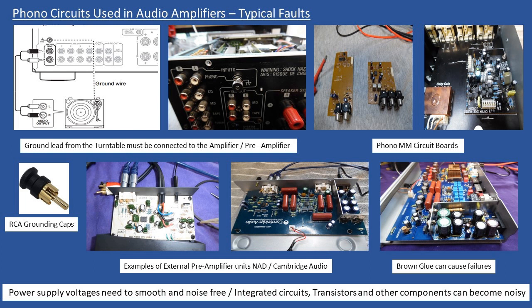You want to localize it down to a specific component, so leave the spray straw in place, and as you press the top, just drop some of the liquid onto the component that you're testing. It ices over, and when you're listening you hear the noise disappear, and you can then reheat the component. As the ice thaws out, or maybe you just hover across with your soldering iron, not making contact with it, just producing more ambient heat, within a few seconds you start to hear the noise come through again.